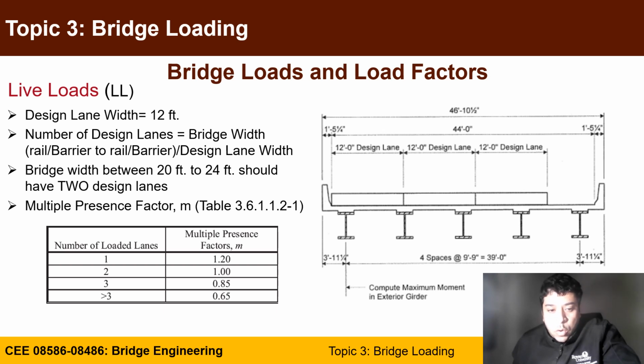So now let's go for more description about live loads. In this example, we will cover live loads, pretty much your first assignment. In Problem number 2, I asked you to lay out in the cross section the spacing between the girders and overhang based on simply supported or continuous spans for steel girder or box girder. We're going to use it very much here. You are now familiar with the general rule to lay out spacing.